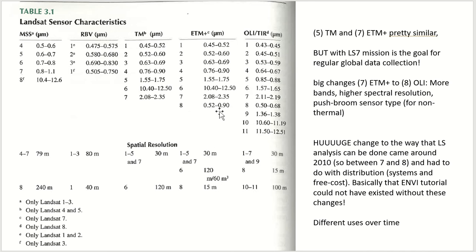And it's got a wider spectral band range, from 0.52 to 0.9, effectively the range of bands 2 plus band 3 plus band 4, starting at 0.52 micrometers all the way to 0.9. Because it's looking at all reflected energy across a wider band, there's more energy to observe, and thus precise differences in measurement can be made over smaller areas. So that's how finer spatial resolution is allowed.